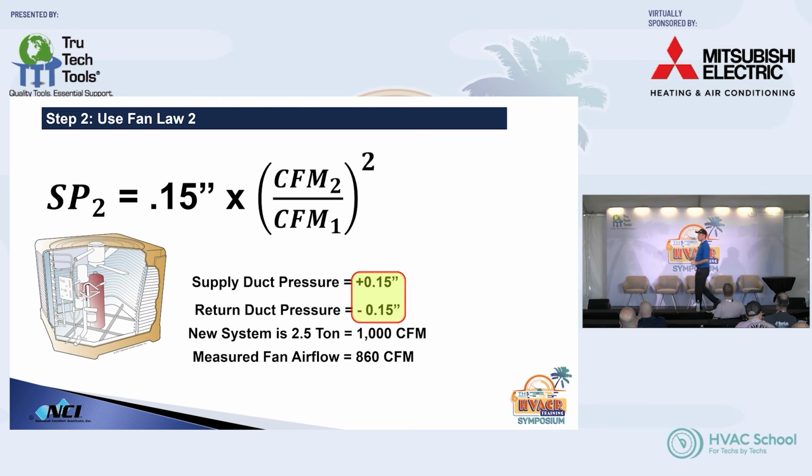When we're replacing equipment, that's our starting point no matter what, because if we were changing a full system, we don't care about what the pressure drops are on the evaporator coil. And if you guys are doing it right, you shouldn't be paying attention to what the pressure is in the filter because you're going to be looking at resizing that filter for something with a lower pressure drop, right?